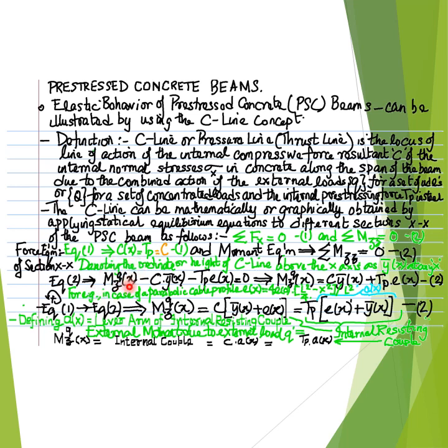capital M subscript Z superscript Q at any location X should be balanced by the bending moments induced by the internal force resultants, that is the internal compressive force resultant in the concrete capital C, and the internal tensile force resultant capital T subscript P due to the pre-stressing force in the pre-stressing steel, resulting in